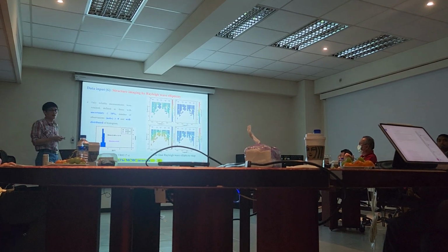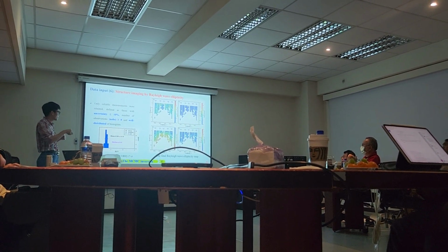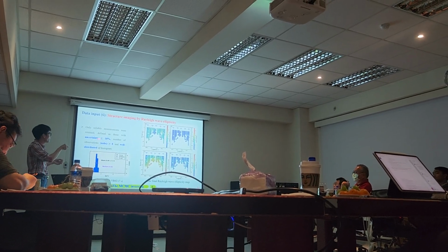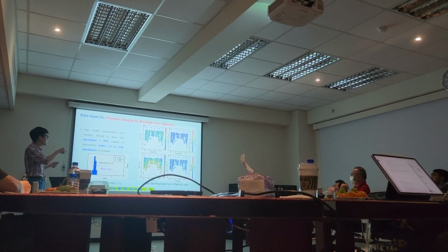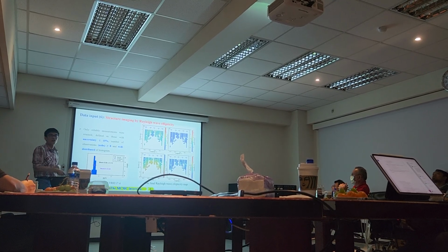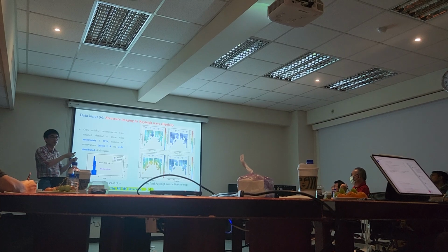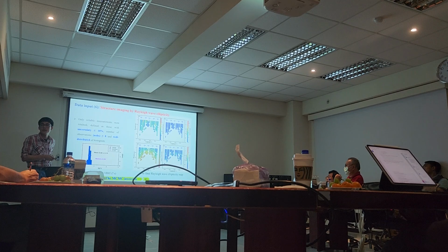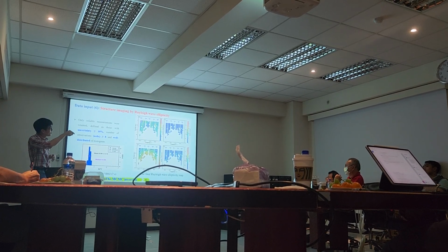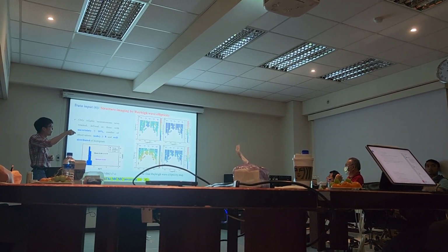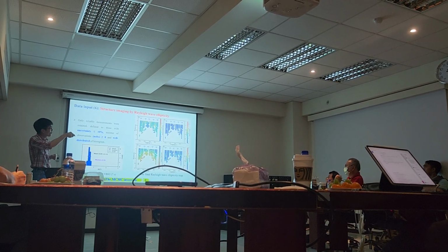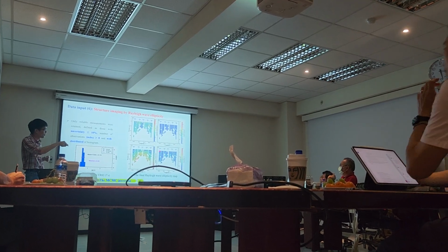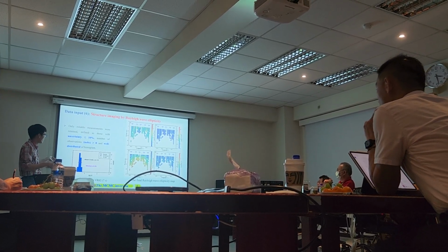We also apply some QC to it, like checking the value distribution. We also use the criteria of uncertainty less than 10% and number of observations of 8, because we have forward and backward for the Z over H ratio, so this is 2 times higher than the threshold for the phase velocity calculation. You can see here the map on the right-hand side, the output result for the ellipticity, and also some other indices like the standard deviation, number of observations, and the uncertainty calculated from those data.